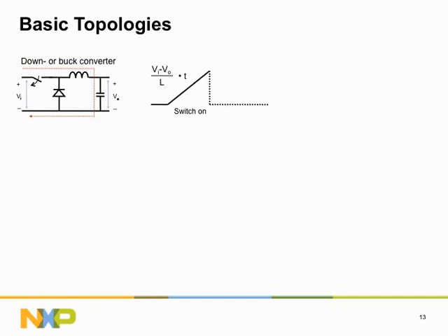This operation phase of a converter, where the first or primary switch is closed, is called the primary stroke. When the switch is turned off, the current in the inductor keeps flowing, but the only path that the current can take is through the diode, which basically operates as the second switch in the power conversion network.